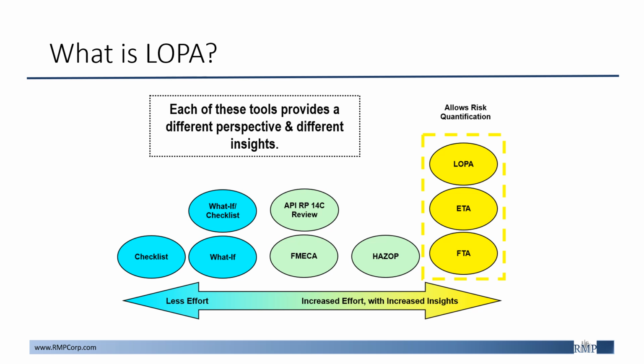The traditional methodology utilized during a process hazard analysis, also known as a PHA, is the HAZOP and LOPA approach. As you see from this image, in the very center, we have a middle effort that is utilized. Moving towards the right, you see a higher amount of effort that has to go into these forms of analysis. To the left, you have less effort, like a checklist. HAZOP's right down the middle.